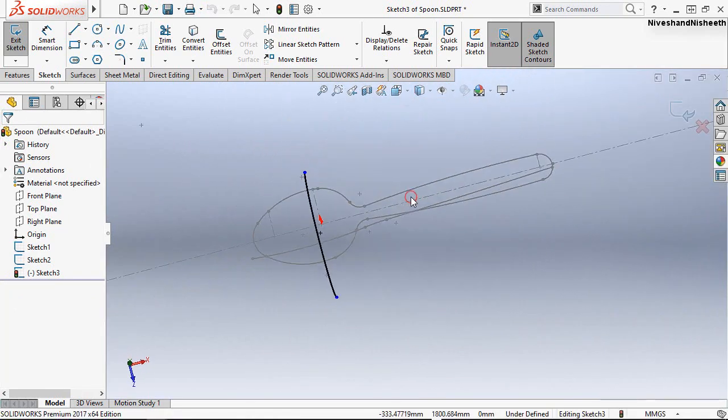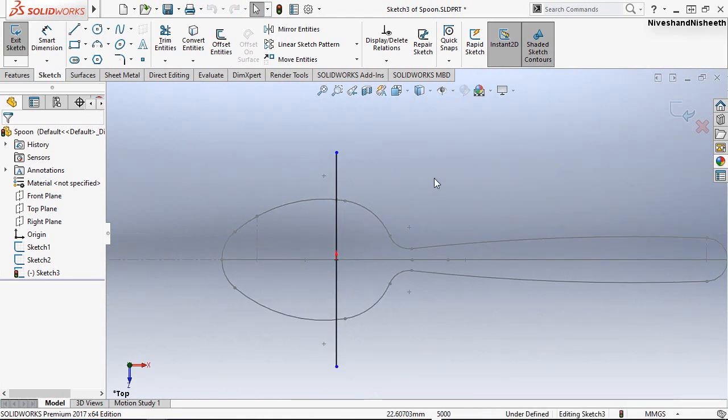See, I want to tell you one thing here. Whenever you make a model with surface tools, you will have to make every surface a little bigger than the base sketch. Only then can you make its perfect shape according to your design as you want. So friends, I hope you have understood my point very well. So let's now proceed with our work from here.